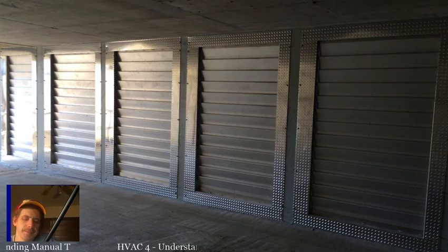Remember, I guess I'll just tell you. Remember, high temperature rise in a furnace is going to create higher flue gas temperatures, right? The high temperature rise across the furnace heat exchanger is not an issue with combustion necessarily, right? It's not going to necessarily cause many issues on the combustion side of things, but it causes other problems that can lead to you having an issue there eventually.